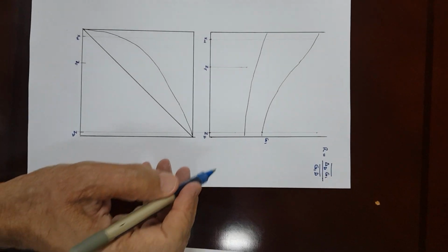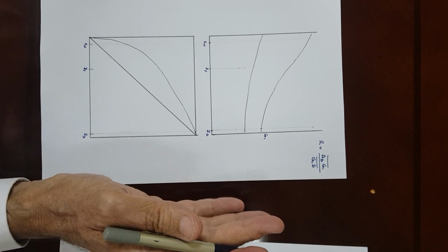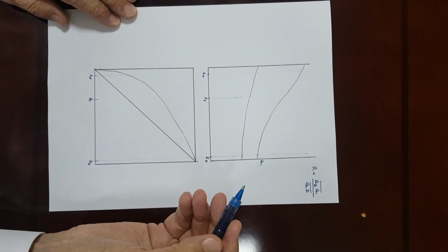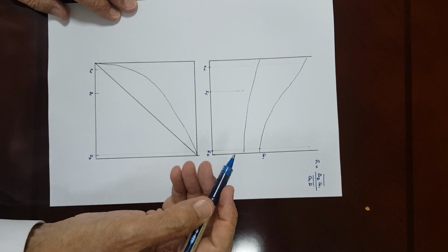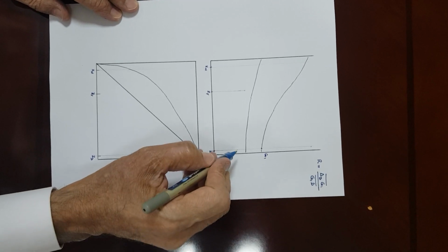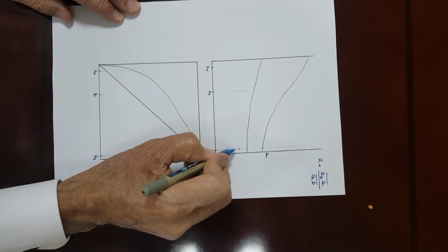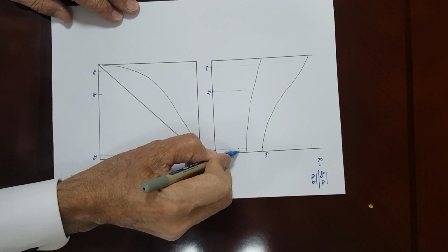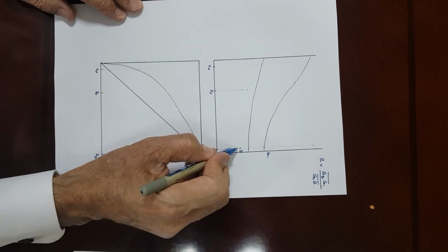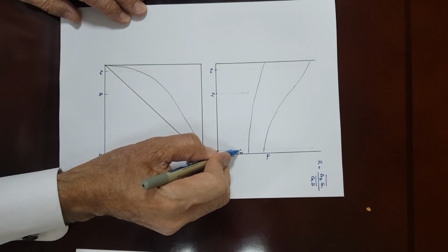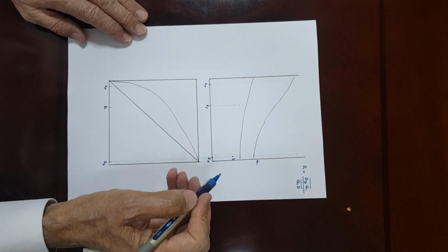Part of the specifications is the distillate's condition. Is it going to be a vapor-liquid mixture, or a subcooled liquid? For example, in this case, let's assume it's a subcooled liquid at a position here, D. We can determine that position based on the temperature and the enthalpy, which can be calculated from the temperature.